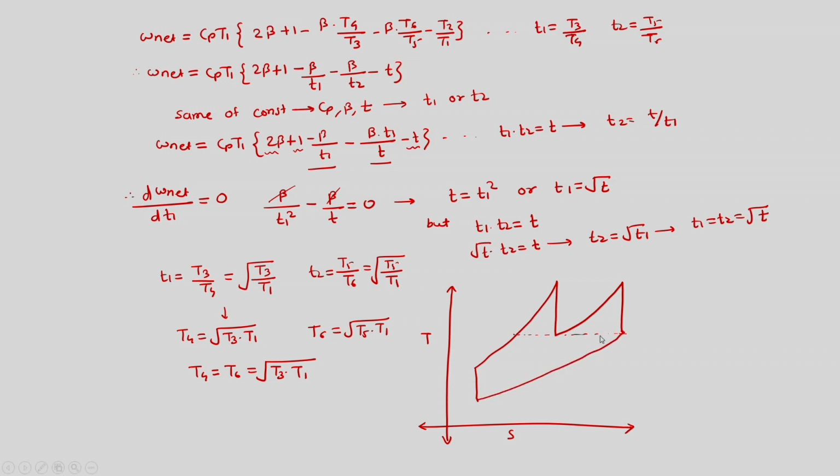So the exit of both turbines has to be same, and practically both the turbine pressure ratios are also same, and since both the turbines have same pressure ratio and exit and inlet temperatures are same, so we mean that WLPT is equal to WHPT. Both the turbines are also doing same amount of work in case of optimum Brayton cycle with heat exchange with reheater in optimum case.